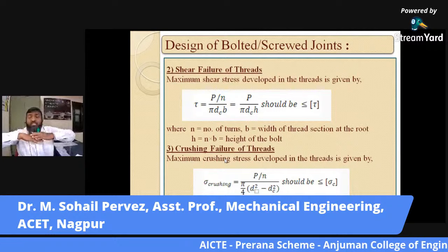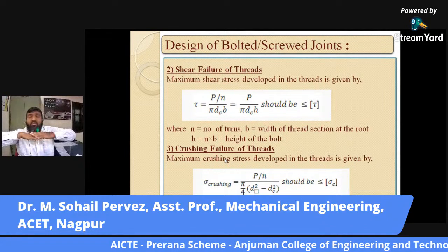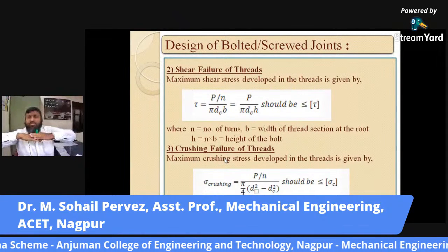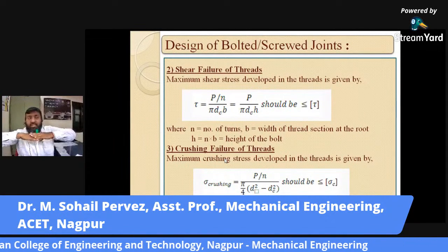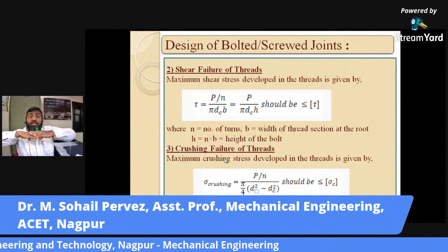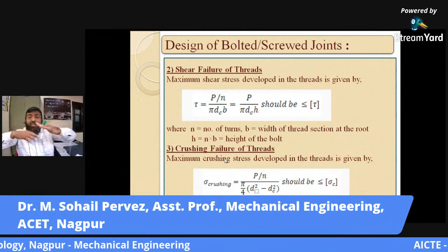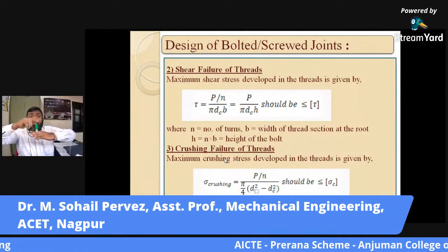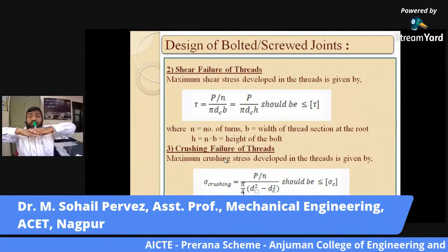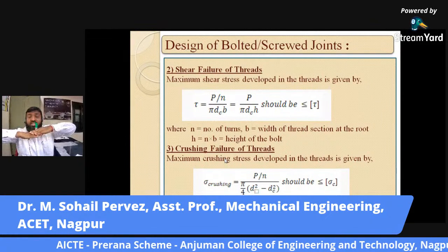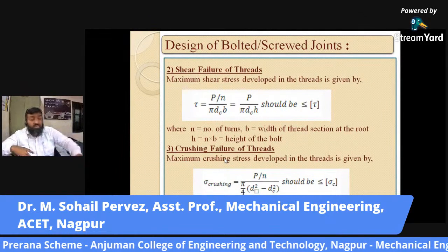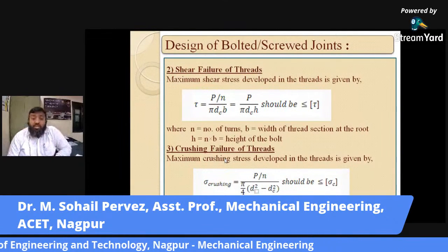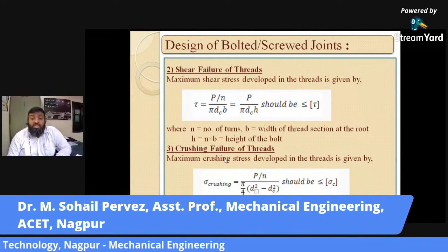Now here also in shear, because in some cases, like you take the example of some foot plates or some truss plates. In that case, the bolt will be fitted in this fashion. Along these two plates, the bolt will be perpendicular. Now these plates will be pulling each other. In that case, this particular bolt will go in shear, a direct or simple shear.